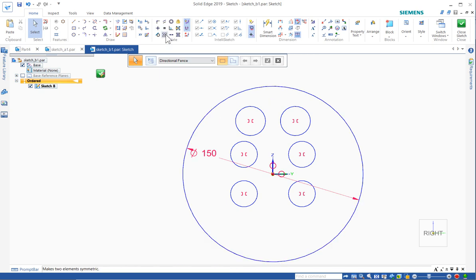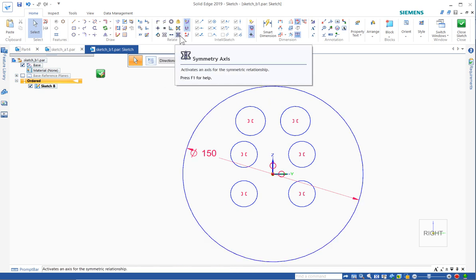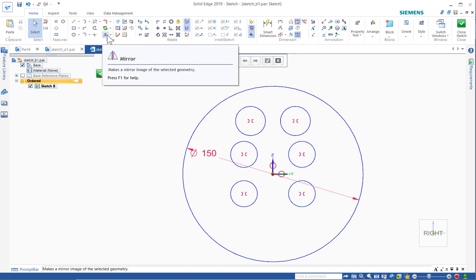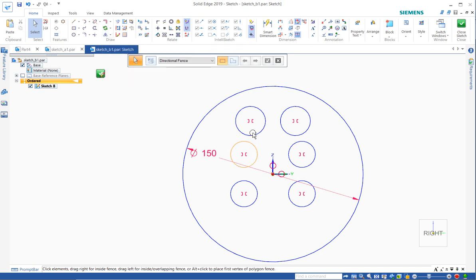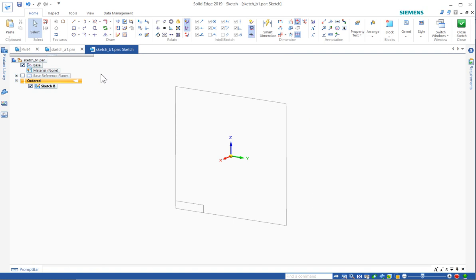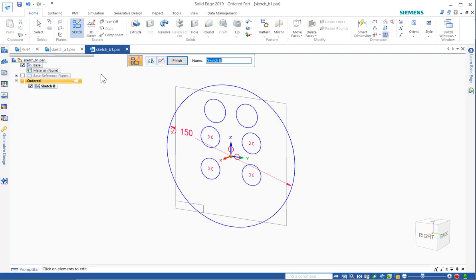But you see that we've created symmetry about two axes, and that's the main point you want to get from this activity, that there are two buttons to apply and to redefine the symmetry axis, and that this command, when you use it, will actually automatically create the symmetry. And you can delete them after if you wanted to just click and delete those little symbols.